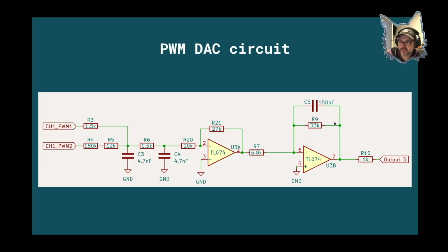I didn't want to have to recalculate the cutoff point of this active filter, so I just left it as is. So if you need to increase the signal in here, what I suggest is change the value of R1. The relationship between this and this resistor will help amplify the signal without having to change any cutoff frequencies for any of the filters. So this is why I changed this from a buffer to an inverting amplifier here.